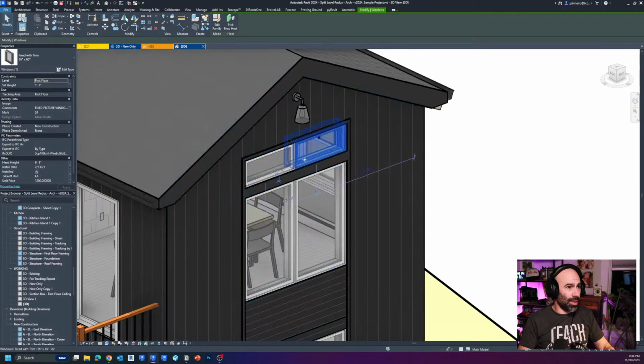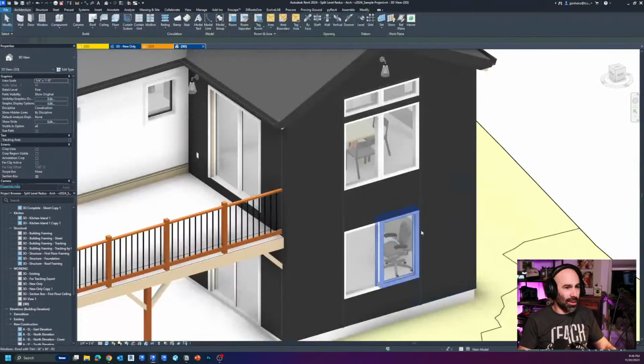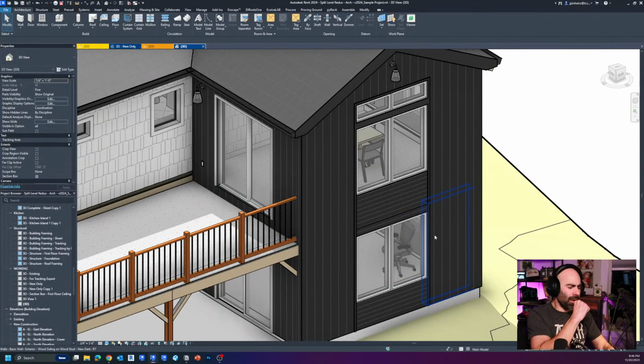And then even here, this one unit was actually like this. The other unit was a double unit there, but you get the idea. So for the most part, that's kind of how it is. It usually starts as a curtain system, and then usually I'll try to build it out the way that we want, with enough room for the 2x6s in between and double 2x6s and all that stuff. I have done it in the past where maybe I'll do a thicker mullion instead of building a bunch of windows, knowing that this is going to be two 2x6s, that's going to be one 2x6, and so on and so forth. But usually I'll try to flip it out to model it how we're going to build it. Your documents, everything's always going to be a little bit better if you model it the way that you plan on building it, so to speak.